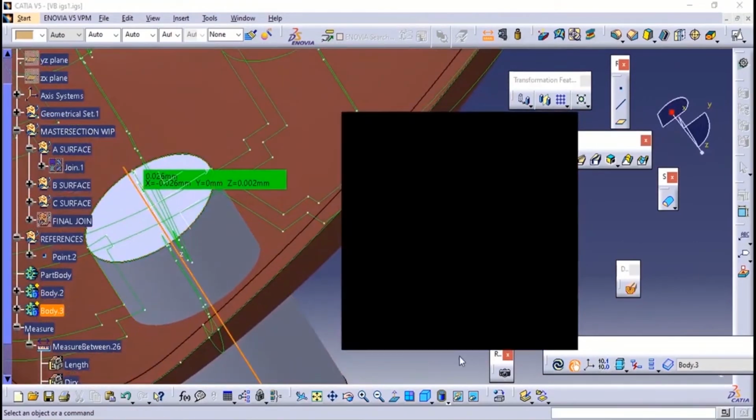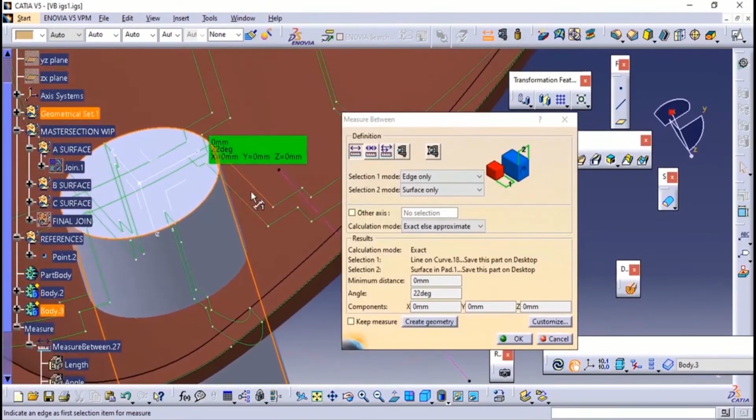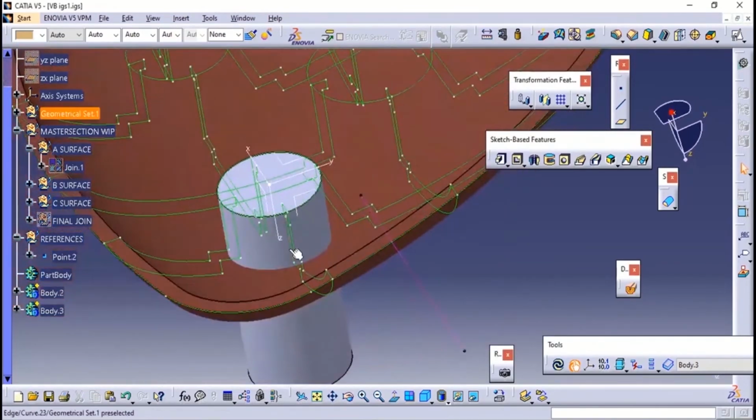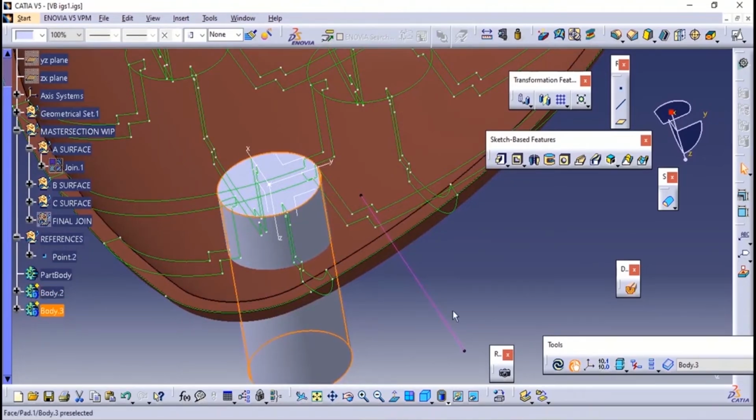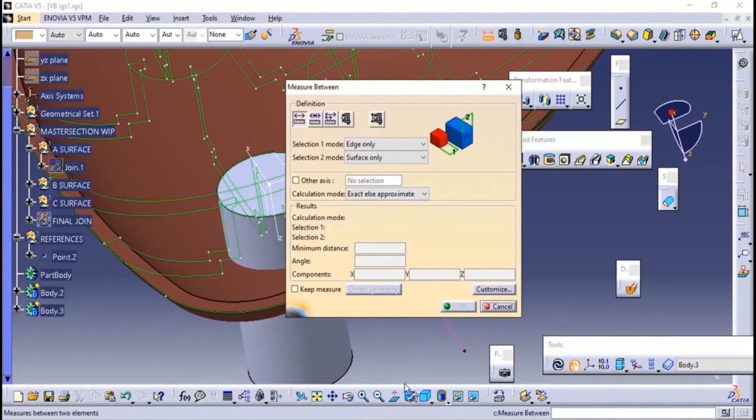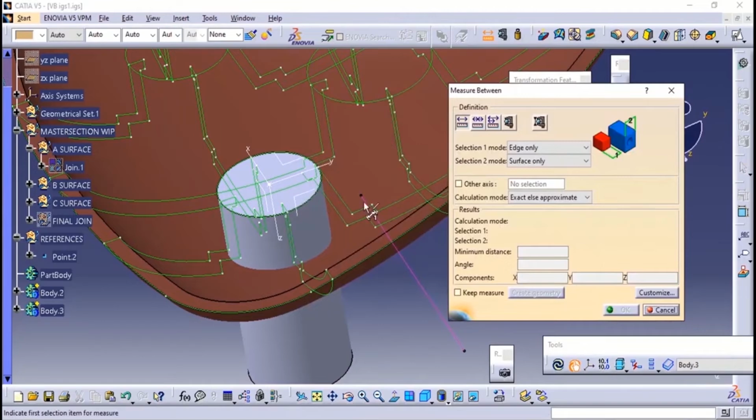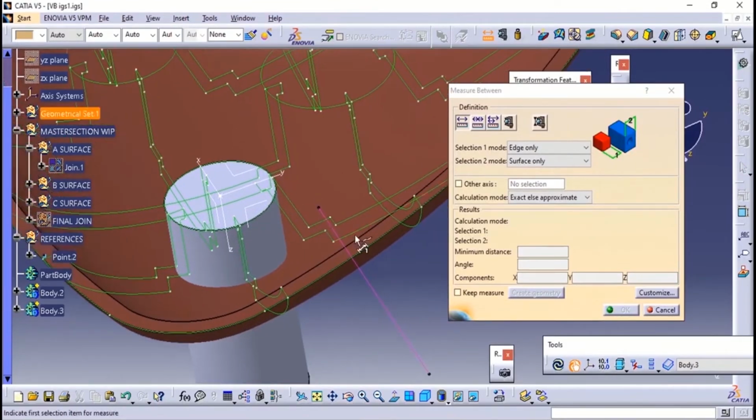This edge, see there is a difference of 22 degrees of angle. Okay, see here it is drafted. You can see the tooling direction. Okay, and this one. So this is drafted actually. That's the reason it is getting elongated here at this area. So we can see the draft angle, how much they have given. So guys, be cautious here. Okay, check the draft angle properly. Here you need to check the draft angle with the master section and the tooling direction given, not with your body.